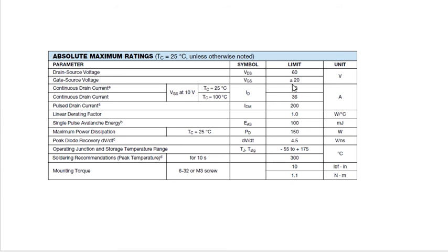But here also you should take the margin. Normally these MOSFETs are not used at this ampere rating because it is very difficult to cool them. You have to provide a heat sink, forced air cooling, sometimes even water cooling if you want to reach this level of current, and this is highly impractical, but these are the maximum ratings.